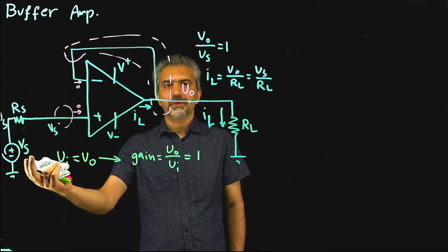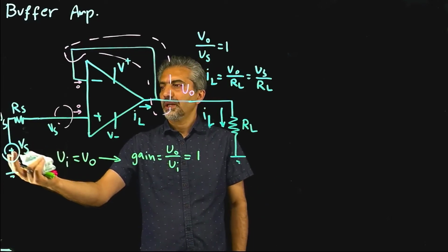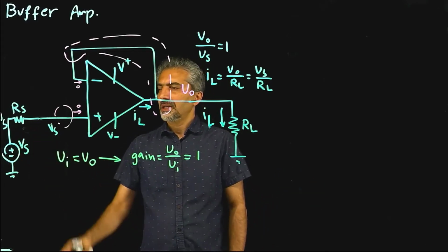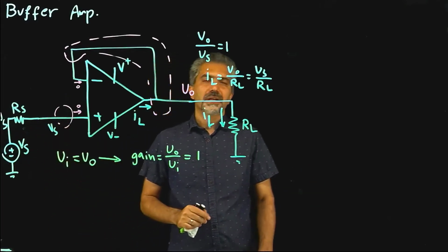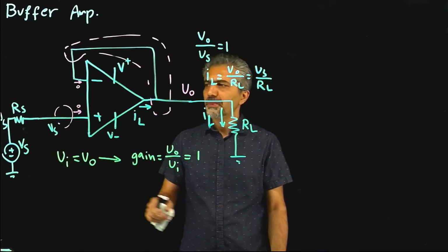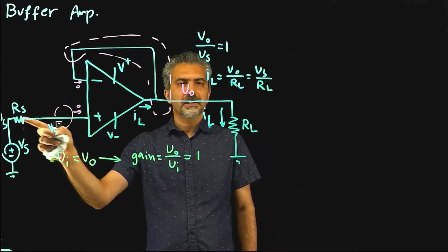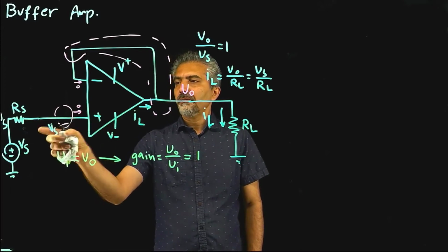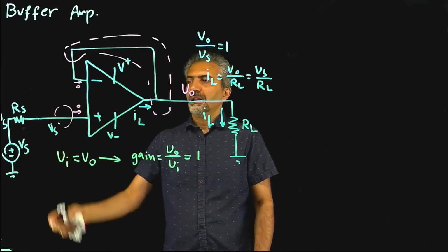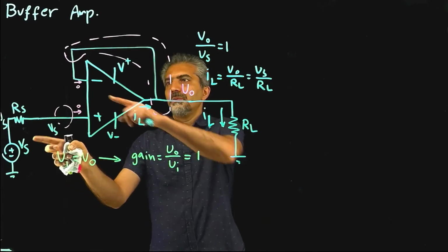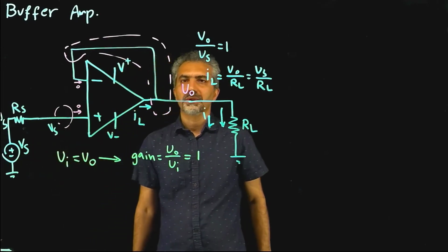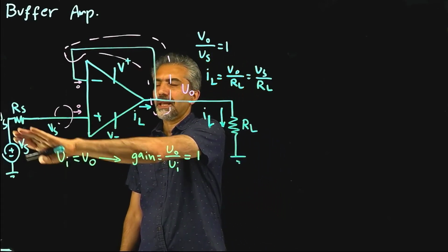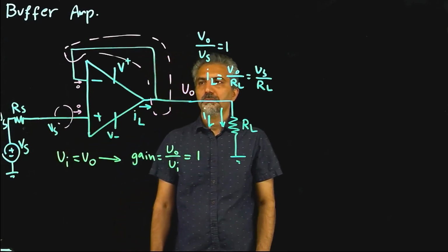There are a lot of components where you, say, take temperature and turn that into a voltage and current using a certain physical phenomena. And in those cases, the signal that you generate is actually a very small signal by nature. And the internal resistance is not too small. And then if you want to take that and amplify it, if the internal resistance of your amplifier is small, then you get a voltage divider. Whereas if you use a buffer, then you can basically maintain the same signal level without losing much.